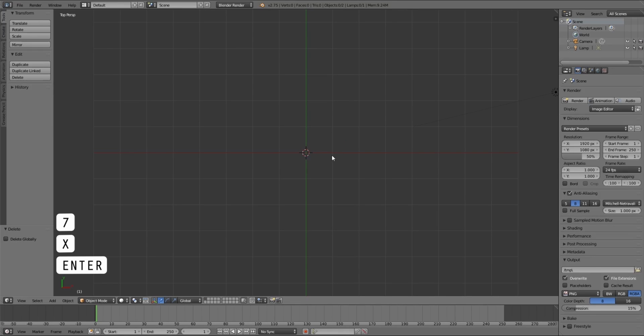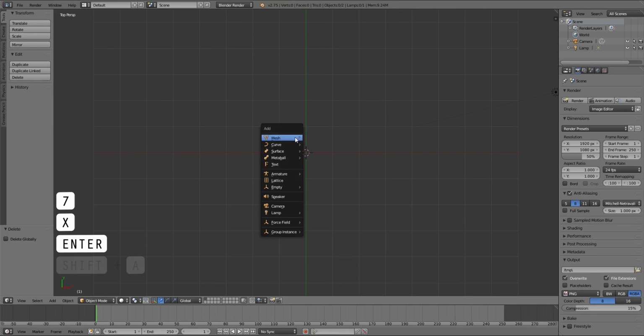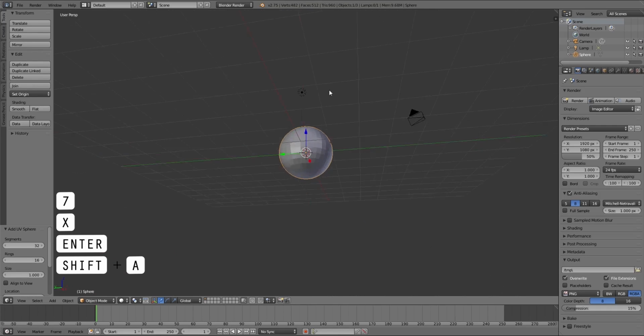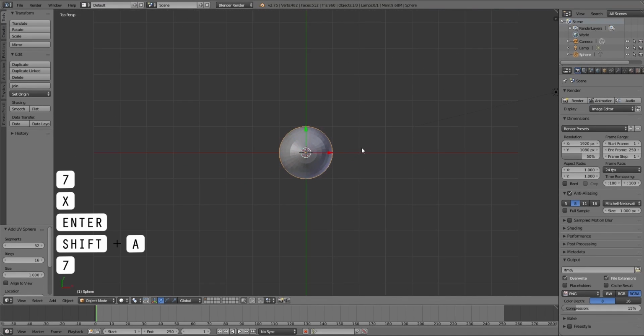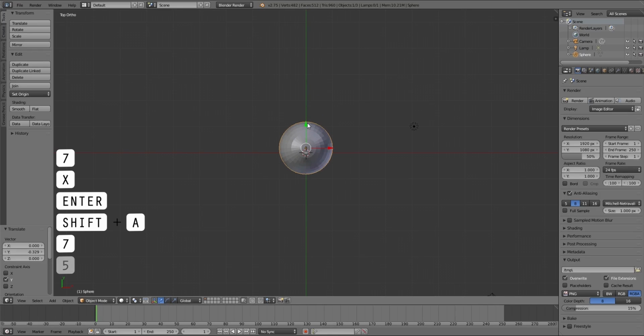And so the first thing we want to create is a petal. So we'll just press Shift plus A. We'll bring up the Add Objects menu, and we will add a mesh into a UV sphere. So now we've got a round sphere. Go back to top view with 7 again, and we want to change this into a petal. So another thing we should do is change the perspective from perspective to orthographic by pressing 5 on the numpad.